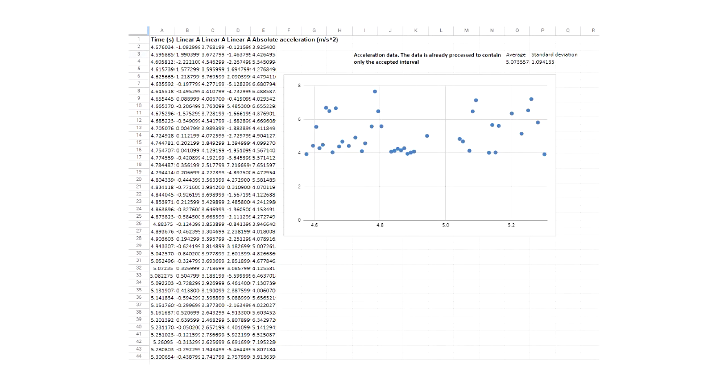Ensure the surrounding environment is as quiet as possible to prevent faulty data. After exporting all the data to a spreadsheet software, we clean up the data and remove any obvious outliers. For acceleration, the start time and end time are demonstrated with 2 visible spikes in the recorded values. We find the average acceleration for the linear acceleration trials, and we also calculate the standard deviation.